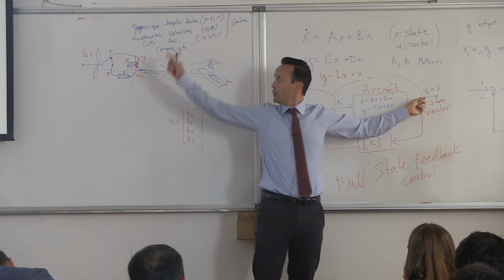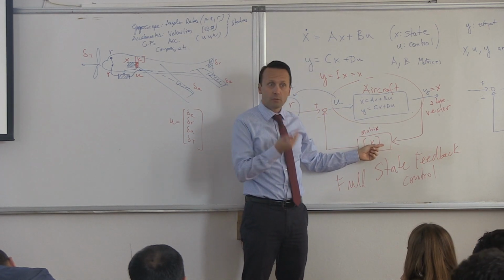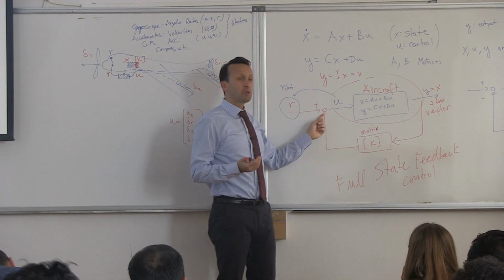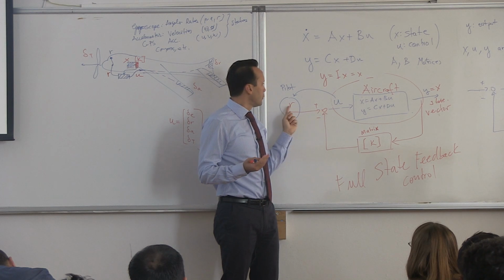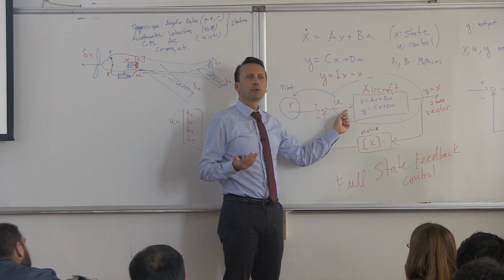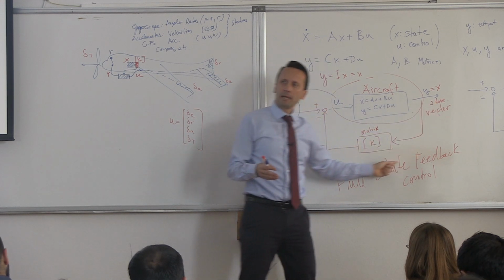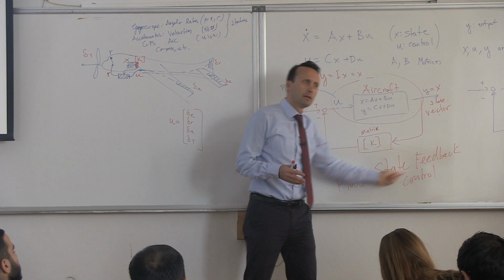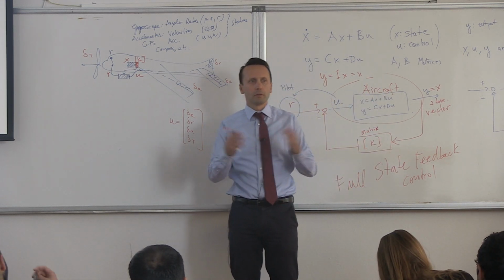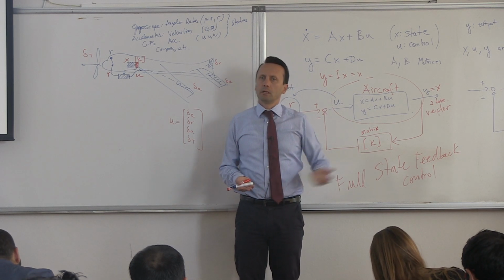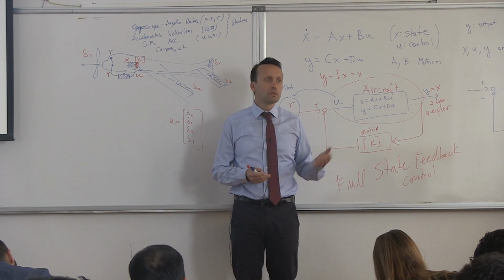We would measure, multiply with a K vector or a matrix or a controller, whatever, subtract it from the pilot controls, and whatever the pilot input here is, it will go to the control surfaces. And then we look at what happened to the airplane. Multiply it again, send it back, do this 50, 60, 70 times a second on the airplane. And what you're seeing here is a typical controller that is used in airplanes.